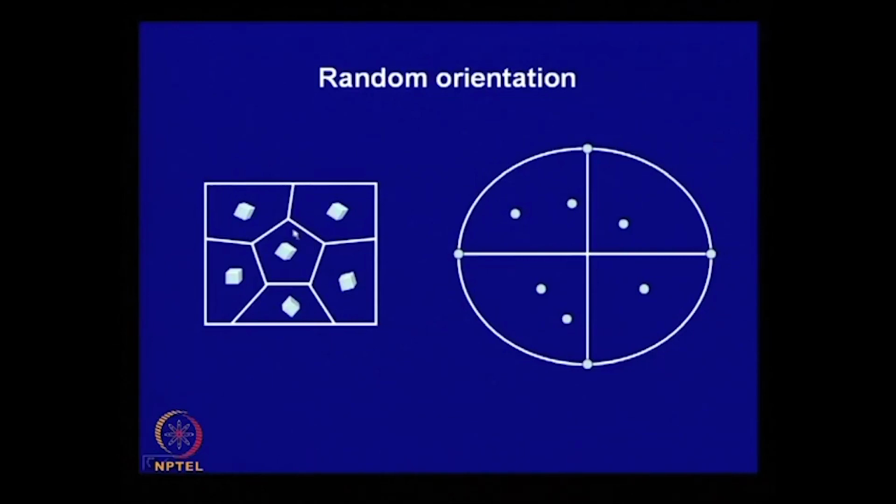So, look at a piece of metal. These are different grains, and each grain is differently oriented, and it is customary to show how the crystal axes are oriented, which is shown diagrammatically here. Now, for a case like this, which is quite familiar, one of the top planes is matching with this. So, in that case, on the standard projection, its cube axes will be represented as these points.